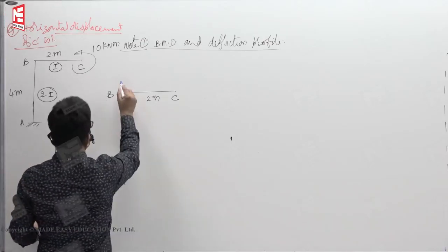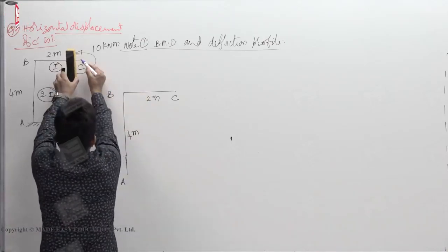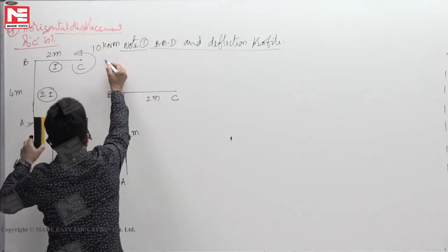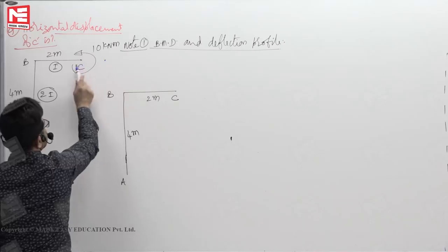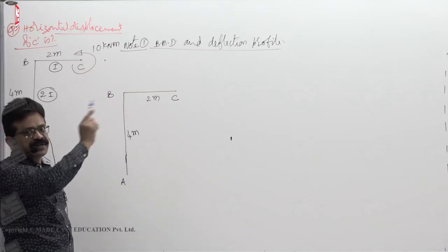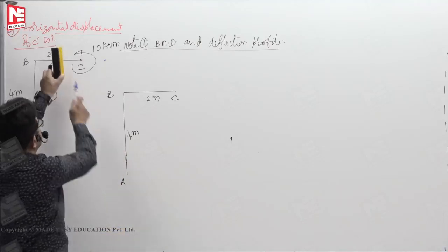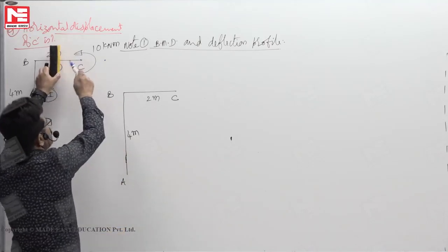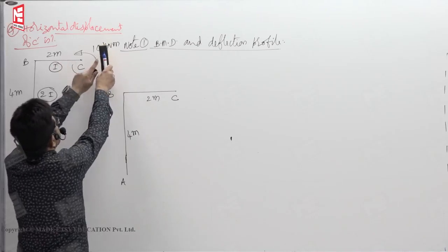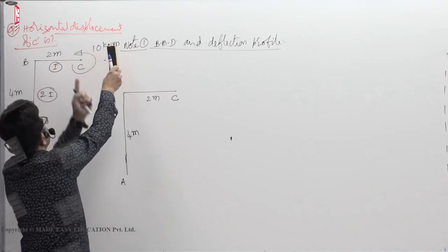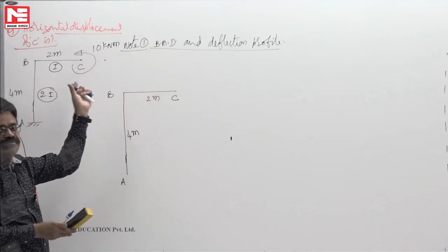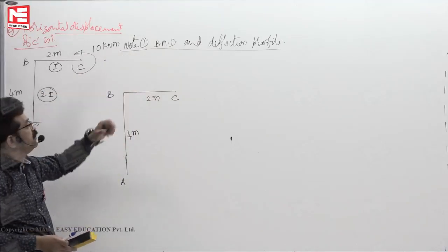So, at two places, even if you stand just to the left hand side of C and look right side, again 10 only. You cannot stand here and say section left side anti-clockwise, it will sag. It will hog, we cannot say. Section right side anti-clockwise, it will sag. But if I stand here and look left side, section left side anti-clockwise, it will hog. Then how to decide?